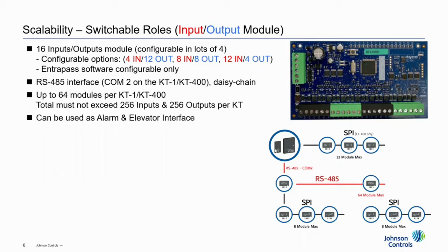Let's say, for example, you have this input and output module installed, let's say near the fire exit. Okay, suddenly, okay, the end user say, oh, I want you to install a smoke detector, okay, at the fire exit. Your problem comes when you do not have additional inputs or spare inputs to connect this fire detector. Then end result, you need to run new cable.